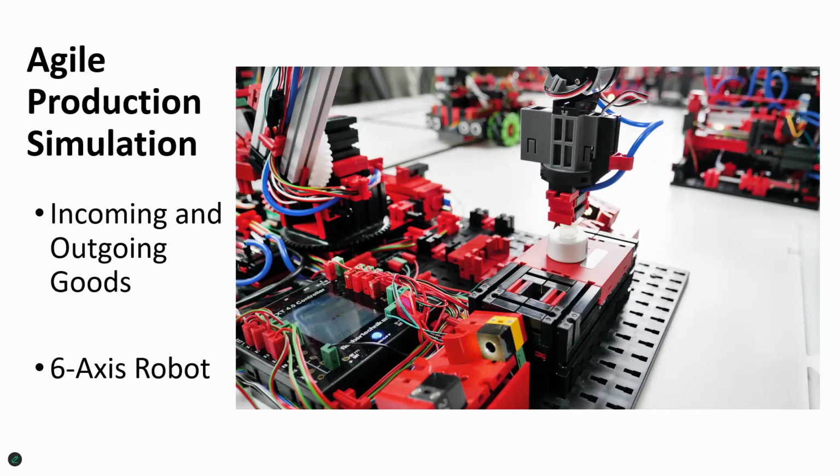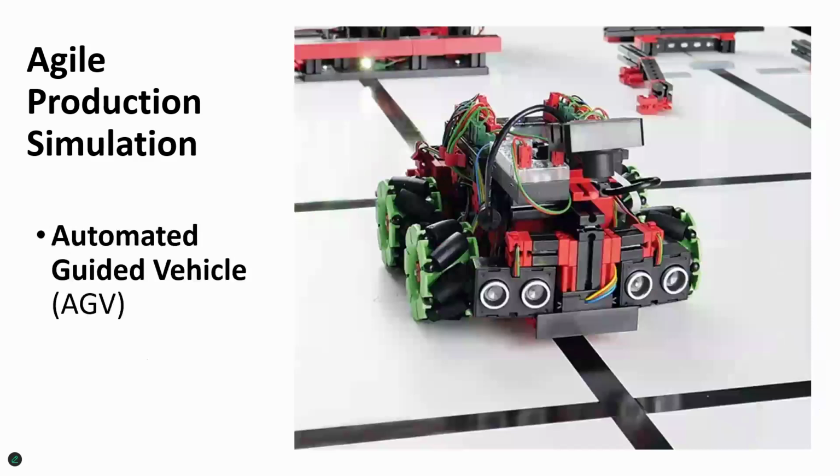The raw material is delivered at the goods receipt slot. It's positioned on the color sensor as shown here for quality assurance control using the 6-axis robot arm with vacuum gripper, and it's then encoded on the NFC reader. Now, the 6-axis robot then places the workpiece we just saw onto the automated guided vehicle, or AGV, for further transport. Now, this module also contains the central control unit, the Raspberry Pi unit, and the environmental sensor, which is used to measure the different environmental conditions for the factory.